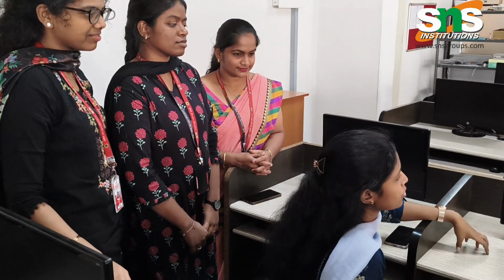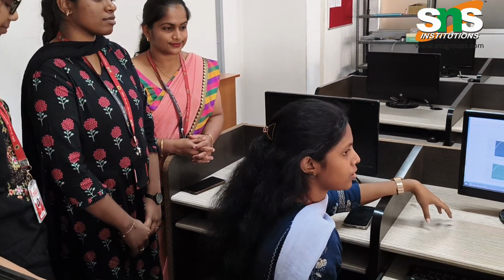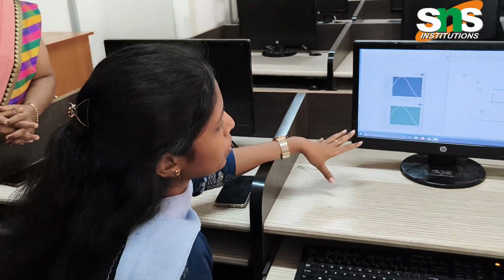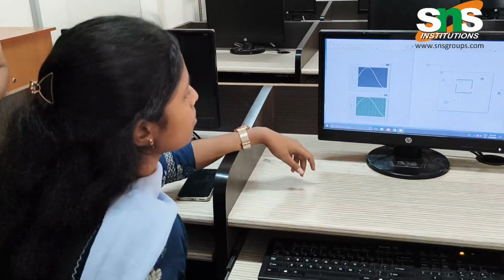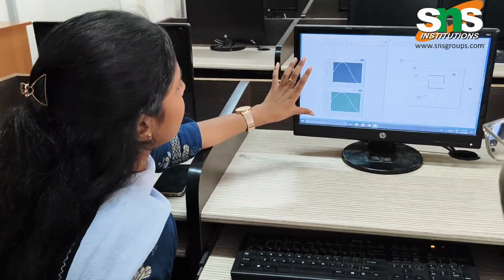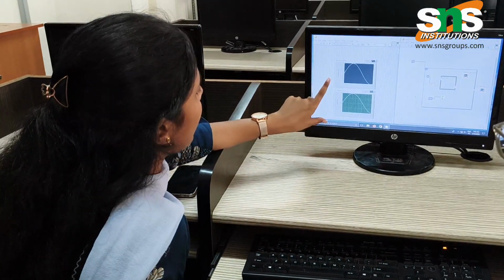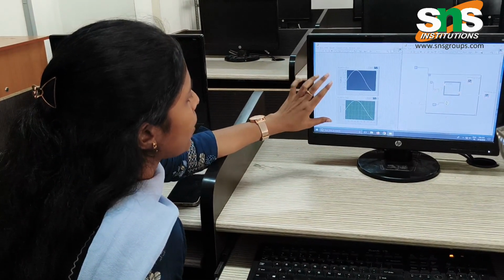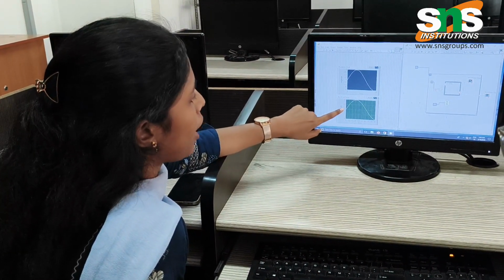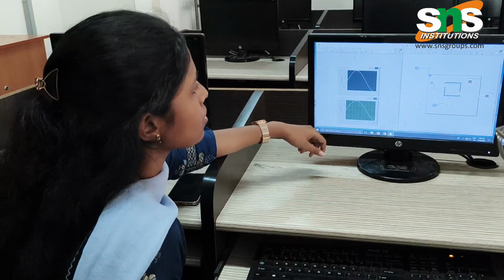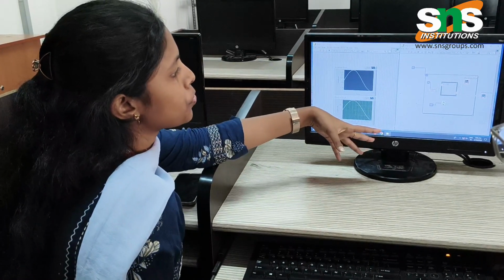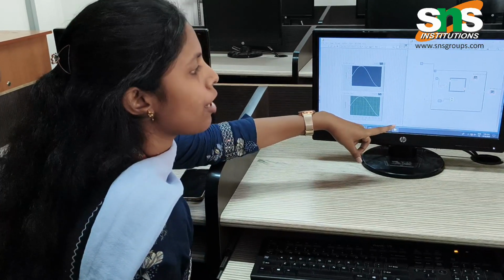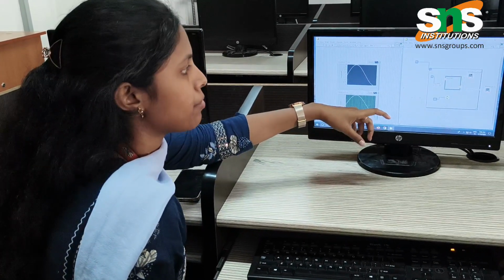In this experiment we are going to see waveform generation using a formula node and expression node. Here we are going to see nearly 5 steps. Our first step is placing an amplitude and frequency control in the front panel, and we add a waveform chart and waveform graph to show the waveform frequencies. And in step 2 we are opening a block diagram panel. In that we are introducing a for loop for continuous wave generation.